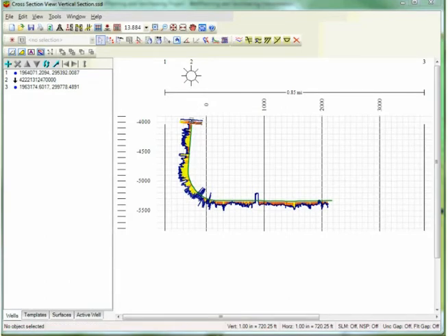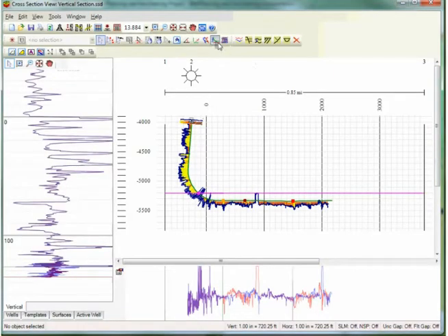smartSTRAT mode is activated by clicking on the smartSTRAT tool in the toolbar. smartSTRAT adds two new panels to the vertical section view and a 2D dip line in the cross-section view to represent the geometry of the dip fault model. The vertical panel displays the type log and the TVT of the LWD log curve. The horizontal panel displays the LWD curve in red and a predicted curve in blue based upon the geometry of the 2D dip fault model, the wellbore, and the type log being used.